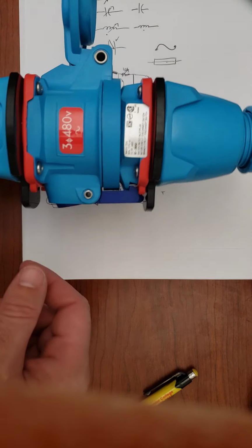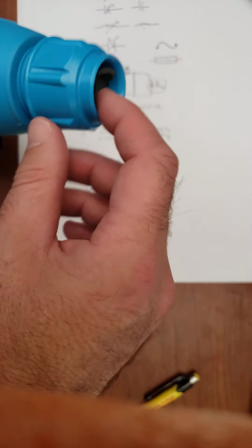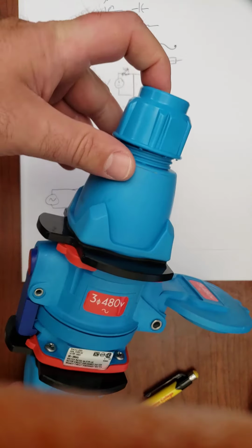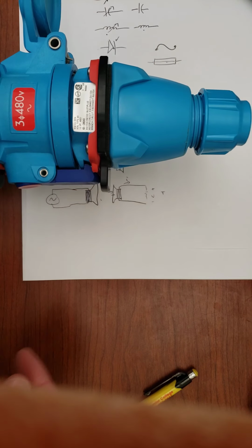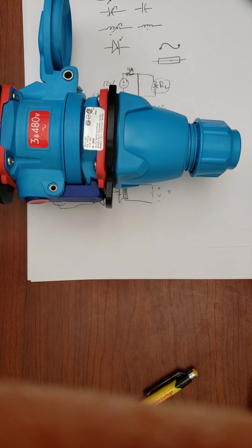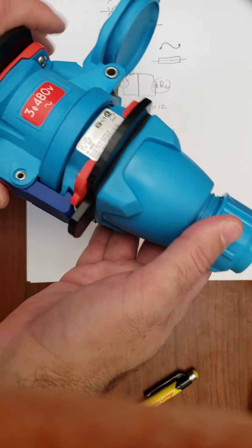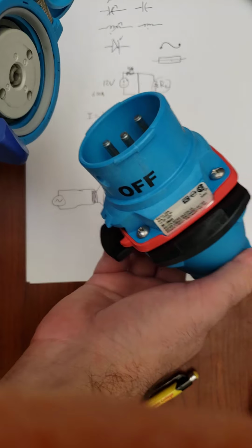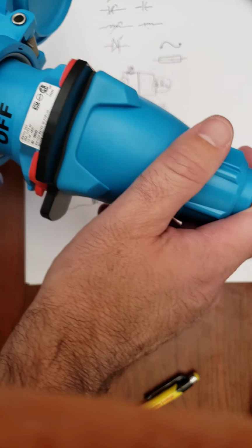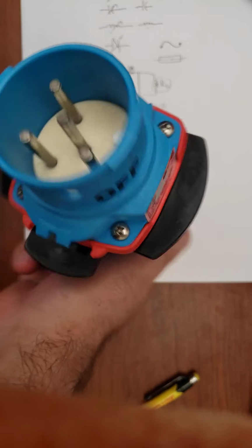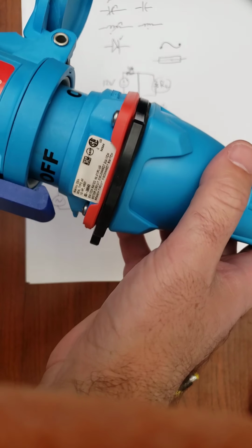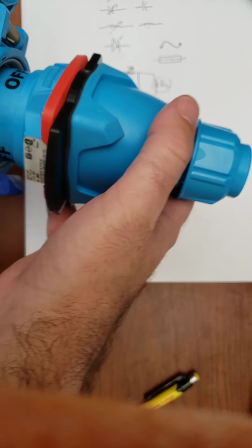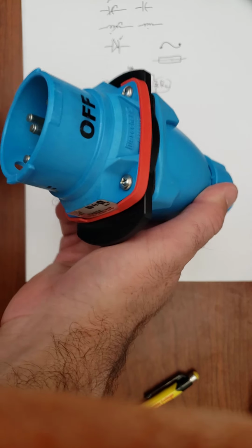So at 480 volts, maybe this goes to whatever piece of equipment I have, and this goes to the power supply, or vice versa. Rather than just walking over and unplugging it, where I risk being showered in sparks from this arc flash, instead I press this button. See, it says off. That's nice to know. Give it a twist. And so the idea is that connection gets broke inside of here, so all the sparks and molten metal and everything else that happens gets sprayed inside of here versus on me. Now they're disconnected and I can just pull them apart without that risk.